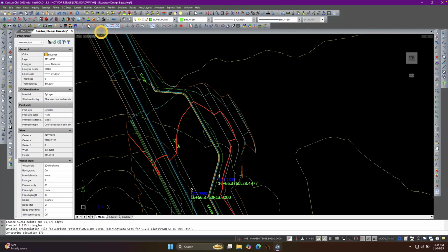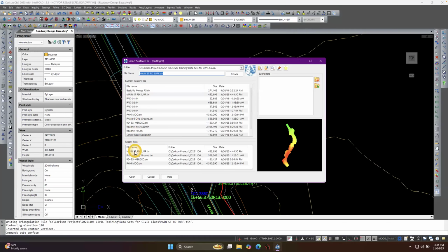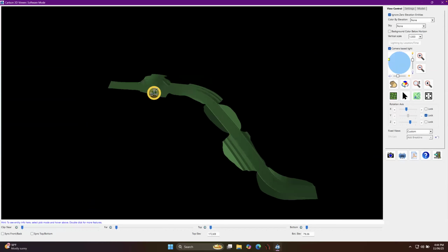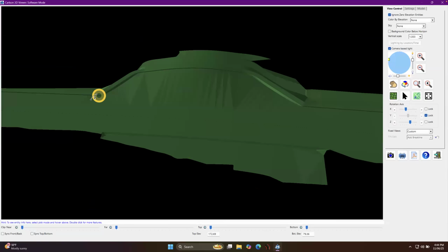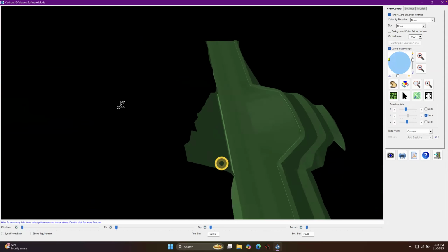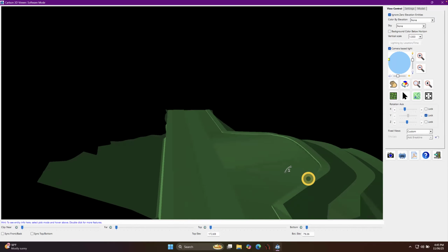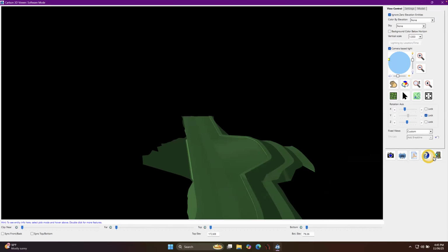There we go. Now, when we look at our road surface, yeah, you see the difference. You see it pushed that out, and it not only followed the alignment of it, but it also raised it up to that point. And I said, hold the offset. So it went from that existing edge of pavement, or the current edge of pavement back here, and then pushed it out here to that high spot here. So that raised that up.